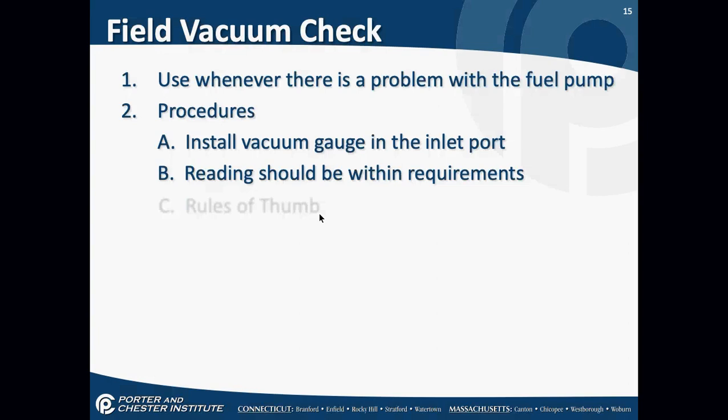10 inches of vacuum on a single stage pump, 15 inches on a dual stage pump, and if I really want a dual stage pump, I might go for 20 if I have a return line. But there's several rules of thumb with it. Again, those are just what I gave you. You have your 10-inch and your 15-inch. The majority of pumps you deal with are going to want to pull a 10-inch vacuum.